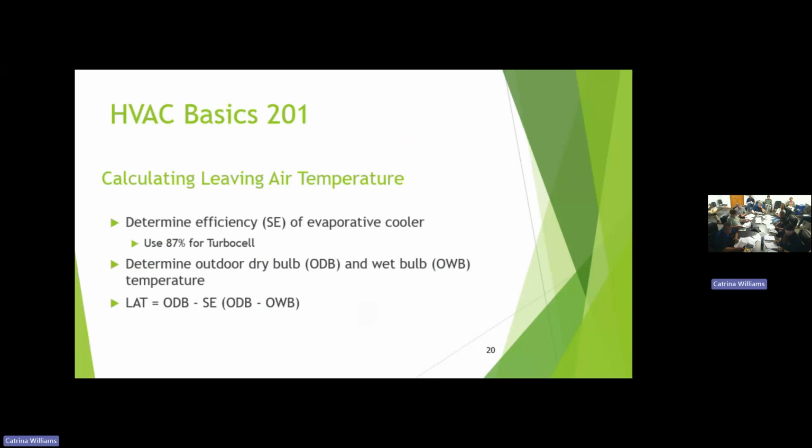And that's a broad statement. 87% is probably based on our maximum CFM. If you pick a lower CFM in the same box, it's gonna be approaching the 90 because you're gonna get better heat transfer at the lower velocities. But we stuck this as our highest number, worst case scenario, that's what we published.